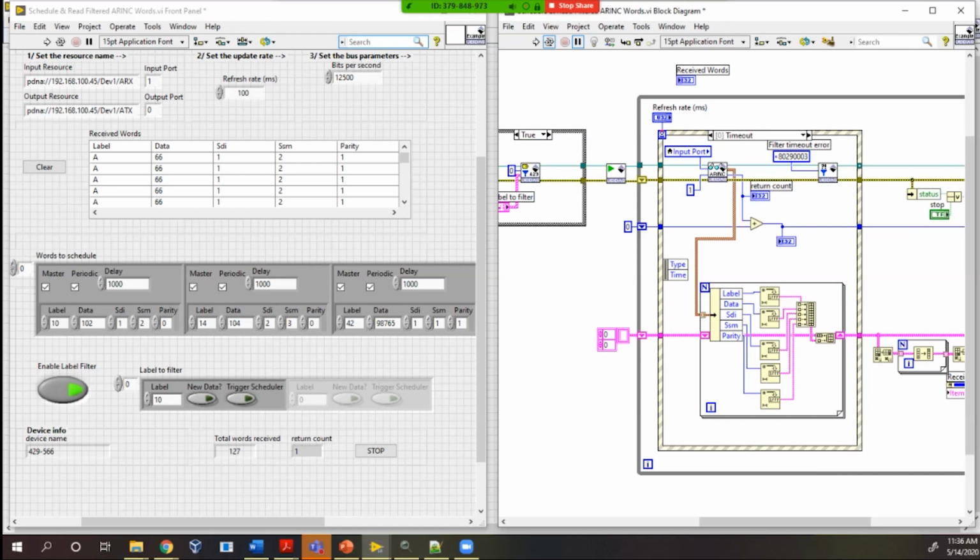So let's see. In a cube system, is the data timestamp synchronized with other analog input channels in the cube? So it can be. What we can do is route the same clock to each timestamp of each board. In a previous masterclass, we talked about where that timestamp counter, or the clock that we're using for the timestamp counter, comes from. We can synchronize it to a PTP or a 1 pulse per second in the case of using a GPS as the main source of time.